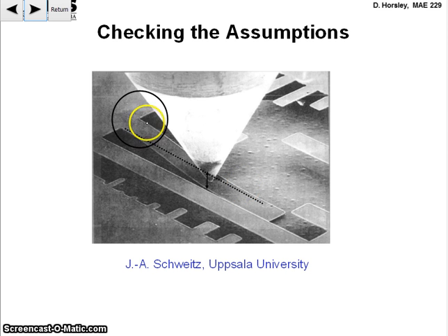In particular, if you have a structure made out of some thin film and you don't know what the Young's modulus of that film is, right? We've talked about the Young's modulus of silicon. You might be working in some other crazy material, I don't know, germanium or germanium oxide, and you don't really know what the Young's modulus is. So you can test that, right? You can make a film with a known thickness, and if you calculated what you think the spring constant is, then you can make a measurement like this and figure out the Young's modulus from that measurement.